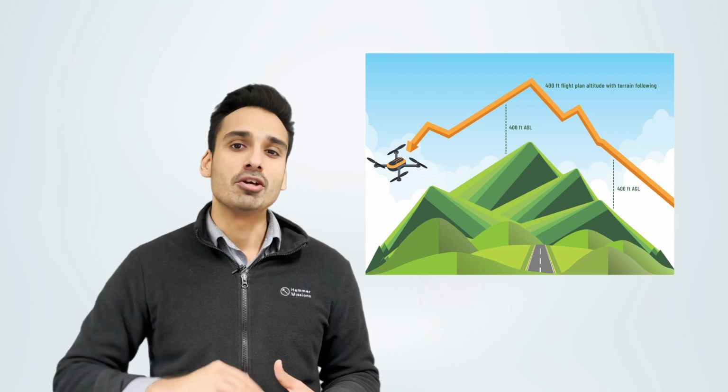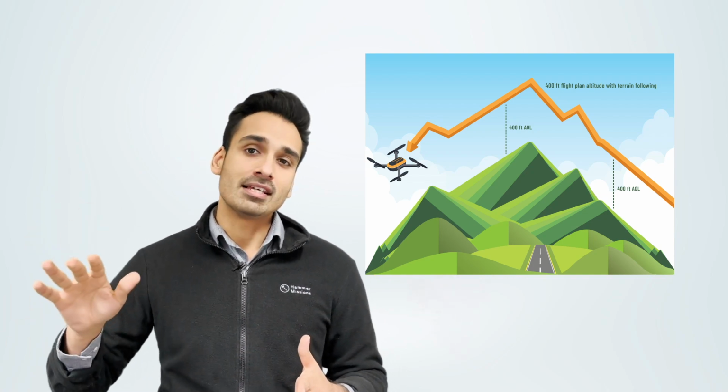Terrain follow. Terrain follow is a name given to a flight where the drone follows the curvature of the surface or the ground. If you've got uneven ground that you're mapping, you want to follow that ground whilst you're capturing images. The reason is you want to make sure that your GSD, or ground sampling distance, is uniform across that uneven plane, and the overlap between images is also not affected. So terrain follow is really important to be able to get GSD and overlap right, which we defined earlier.